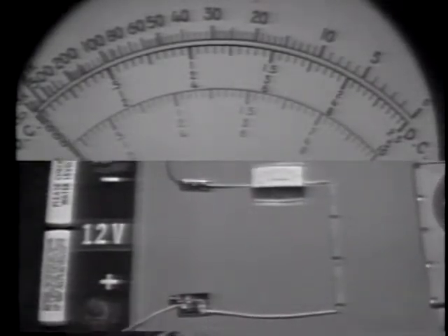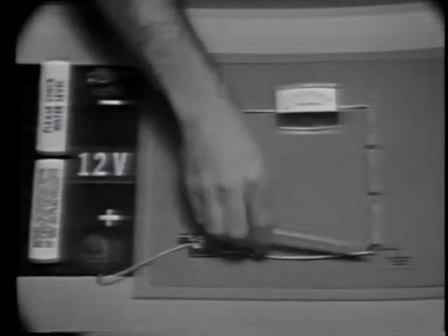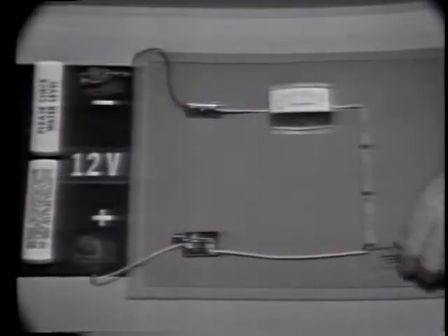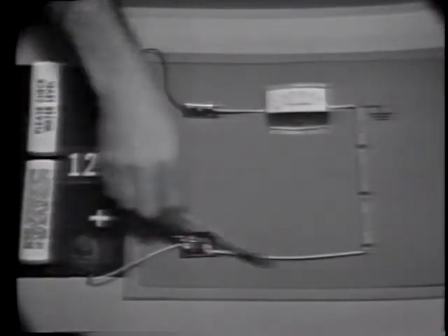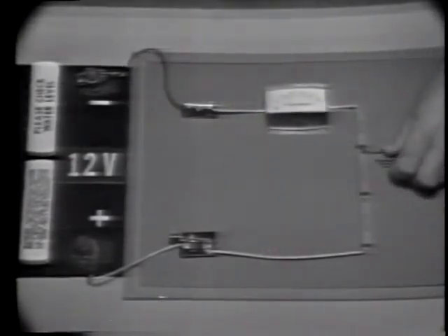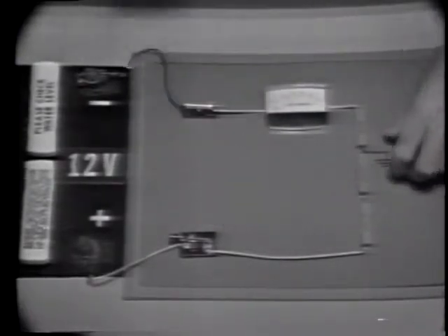We should also remember that different polarities can be obtained from a voltage divider. For example, if we were to ground the circuit here, all of the voltages in the divider would be negative with respect to this ground. If we move the ground up here, all of the voltages are positive with respect to ground. And if it's grounded anywhere in here, of course, we would obtain both negative and positive voltages. Well, in this lesson, we won't be concerned with polarities, but keep in mind that different polarities are available.